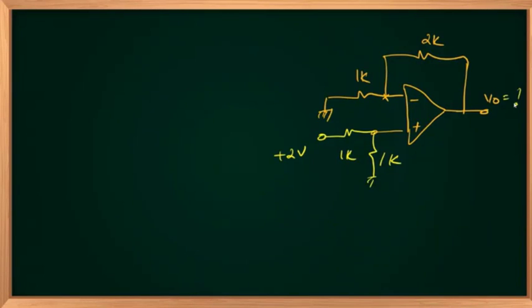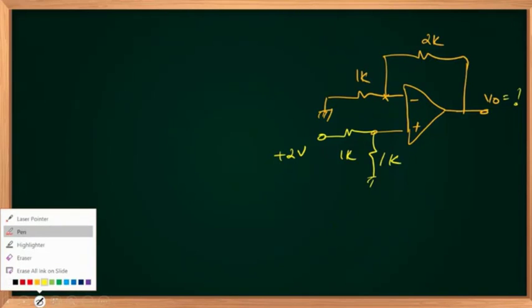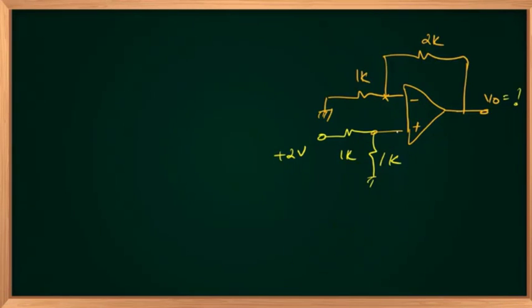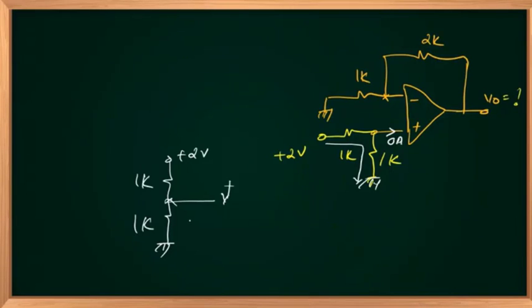So some of you will be having doubt how to solve this quickly. Let me explain. Is there any current into the op amp? This is 0 amperes. No current into the op amp implies same current flows through these two 1 kilo ohm resistors. So it's a kind of circuit like this. Two at the end, this is grounded, and this is my V plus. Resistors are equal, 1K and 1K. Then what about my V plus? It divides equally. 2 into 1K divided by 2, so 1 volt. So this is 1 volt.